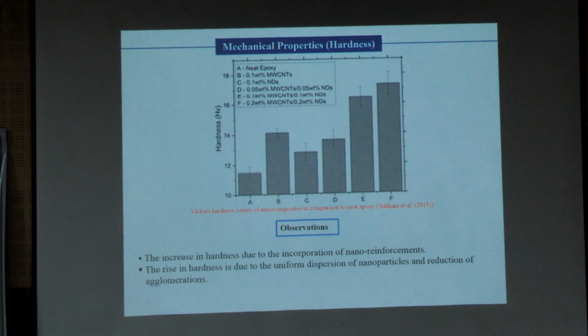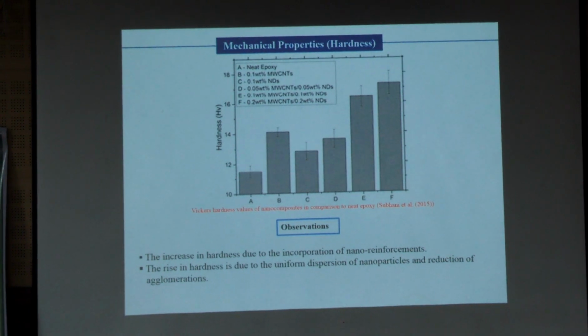Okay. So at some part the hardness will be very high and at some part the hardness may be less. So we have to add the nanoparticles till you get the uniform distribution. Suppose you are not getting uniform distribution, you have to stop there. That is why we test with different weight percentages of the nanoparticles, whatever it may be. So sometimes, depending on the matrix material and the type of nanoparticles, the weight percentage varies, right.